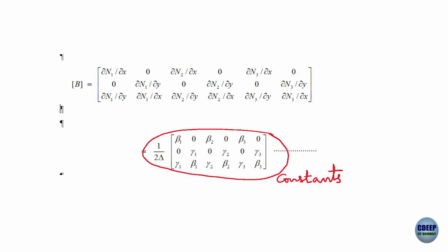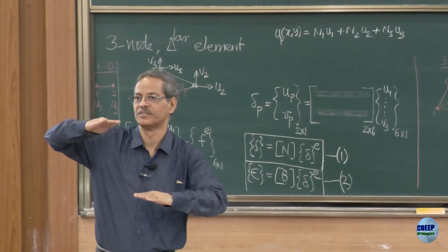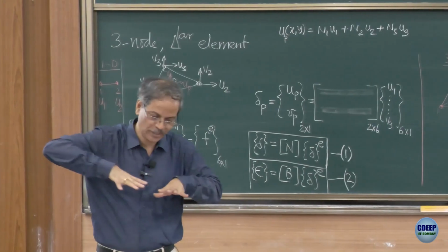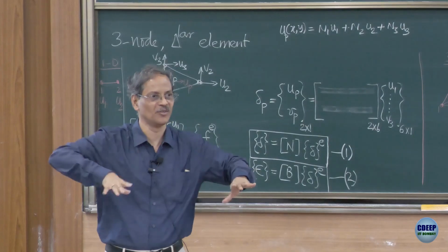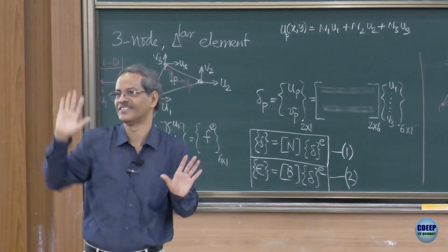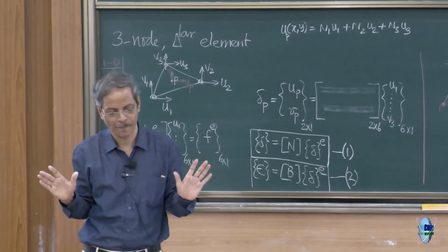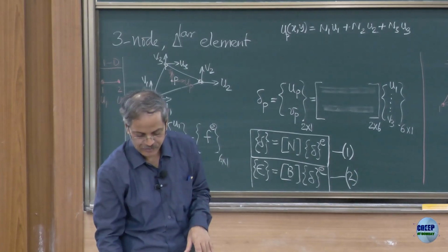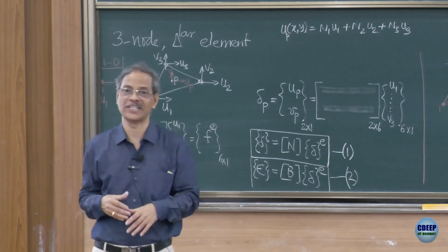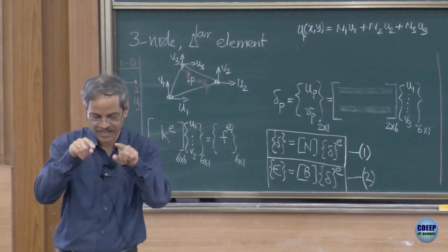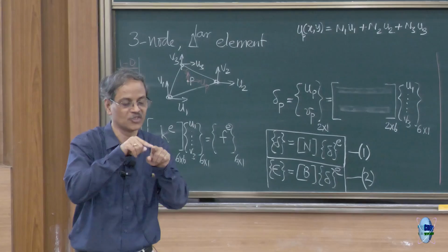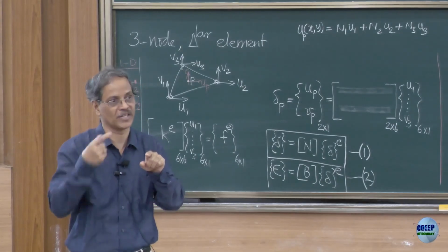Like we had with one dimensional element, when you solve the problem, your approximation to stress will be like a staircase. This will be a two dimensional analogy. It would be like steps, okay, in a planar version of that. That is all that you are going to get with this element. Okay. So, constant strain, constant stress. Now, I bring in stress strain relations. I have found out displacement at a point, okay, and then I am now finding the strains. Next step will be the stress.